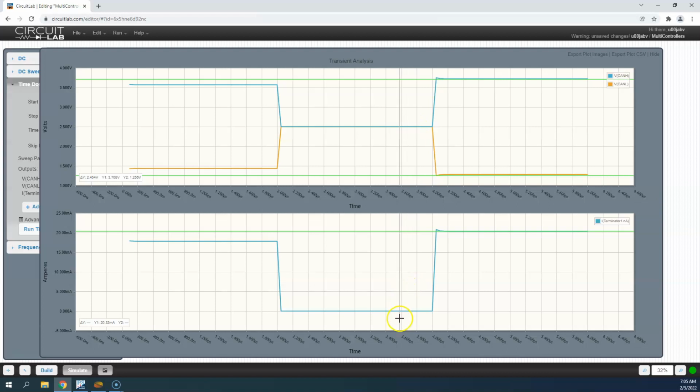That causes the current, as we can see down on this lower trace, to be 0 amps. One thing to notice is that when only one controller is transmitting, we have a current value of 17.79 milliamps, 17.79 thousandths of an amp. When all of the controllers are transmitting, all the other 5, the current increases from 19.79 to 20.35 milliamps in this case.